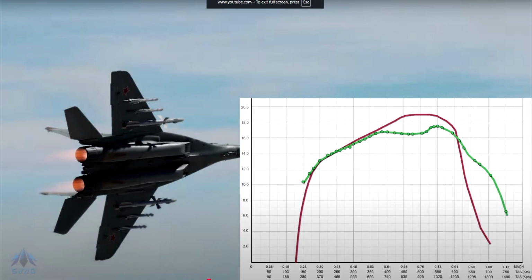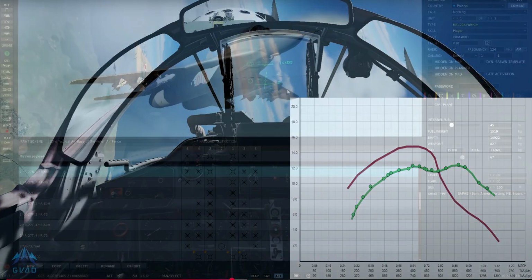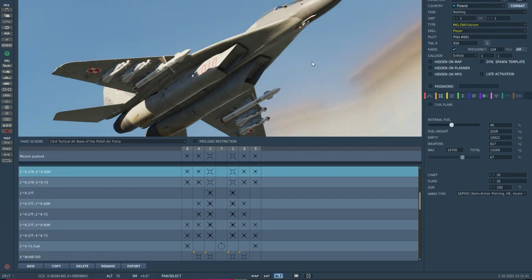First, the fuel load. The rate of turn is quite sensitive to aircraft mass, yet for some reason the test assumed a rather adventurous 90% fuel, while the reference documents clearly specify 1,500 kilograms, about 50%.